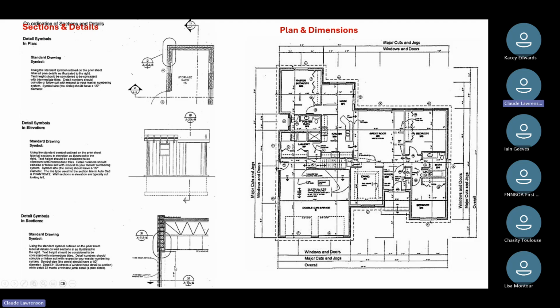And then something more on the commercial side of things. We see this would be more of a commercial building with an open web steel joist, a drop down ceiling, okay, suspended ceiling. There's a window over here, and we can see that part of this masonry wall goes above this, we'll call it flat roof plane. And to me, when I read this, I see there's rigid insulation with probably some type of ballasted roof membrane on top of that particular section detail.